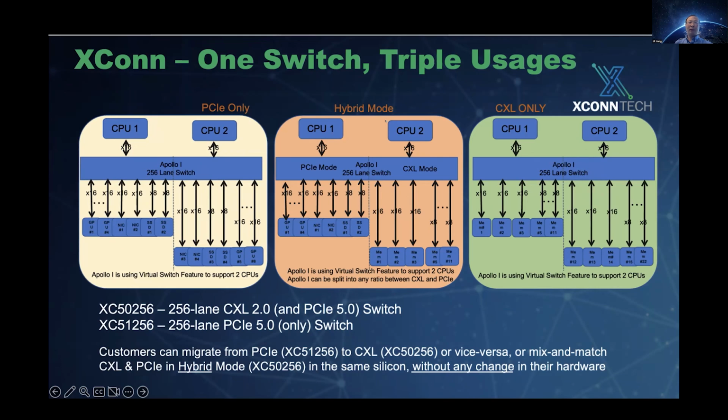The hybrid mode can operate half as PCIe and half as CXL, or you can program it to be one third PCIe and two thirds CXL. That's totally software programmable.